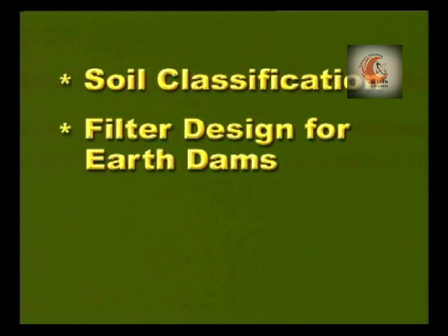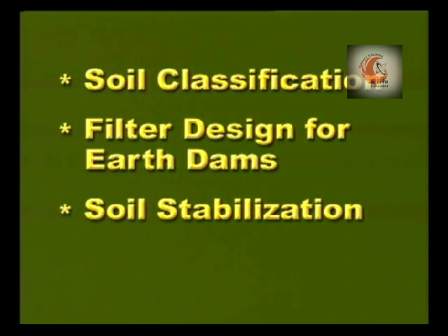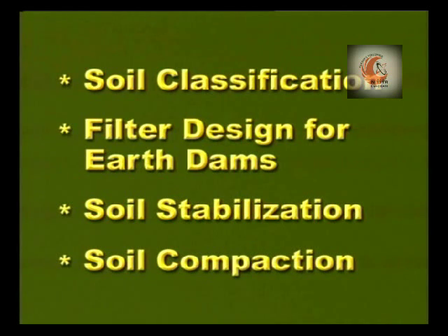Soil usually consists of particles of different sizes in varying quantities. The particle sizes and their distribution in a soil influence the engineering properties of the soil. The different particle sizes and their distribution can be determined by mechanical analysis. The results of grain size analysis are widely used in soil classification, filter design for earth dams, soil stabilization, soil compaction, etc.